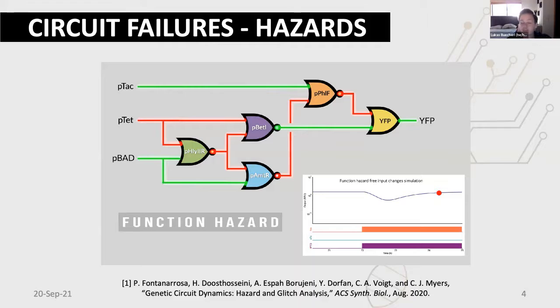There are similar problems in asynchronous electronic circuit design. Usually in electrical engineering, you use synchronous circuits, meaning you have a clock, and the speed of the clock is basically determined by your longest, or critical, path. Every time the clock hits, you update your states, and then you don't get this glitching behavior. That has the advantage that you don't see glitching, but the disadvantage that it's slower, because you always take the longest critical path.